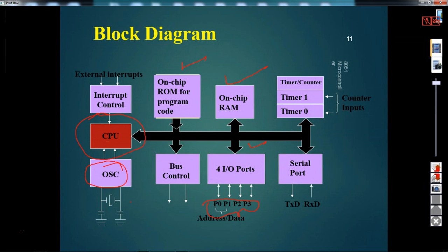and in a microprocessor system we do this with the help of the 8255, which has only 3 ports, port A, port B and port C. Each port has 8 lines, right? And then on-chip timer and counter, whereas in a microprocessor based system we used the 8253 timer. This is also on chip, and then the serial port.